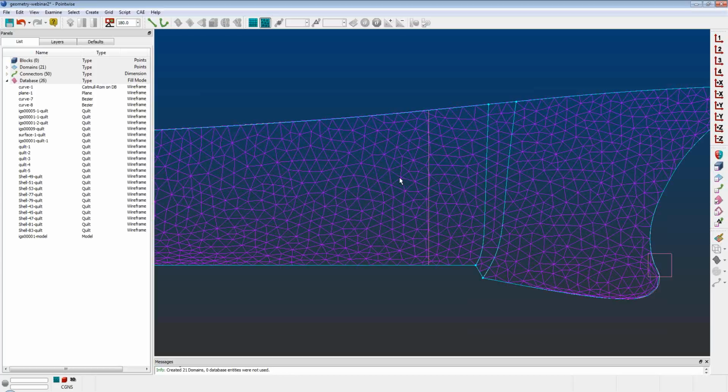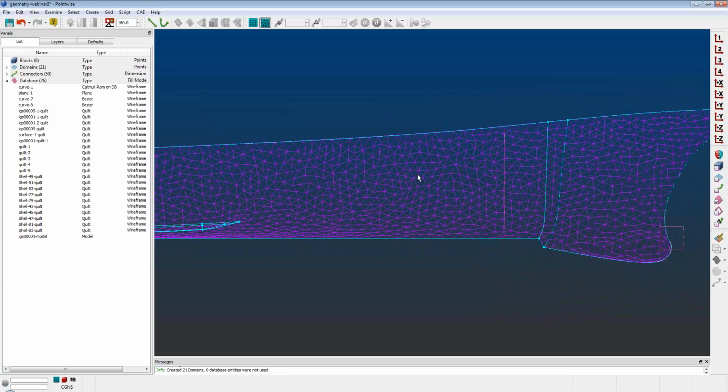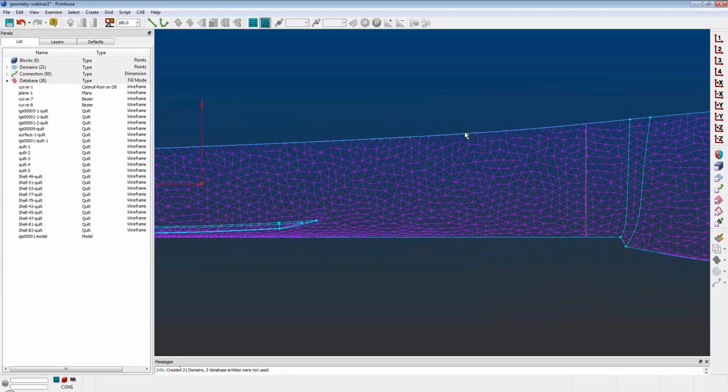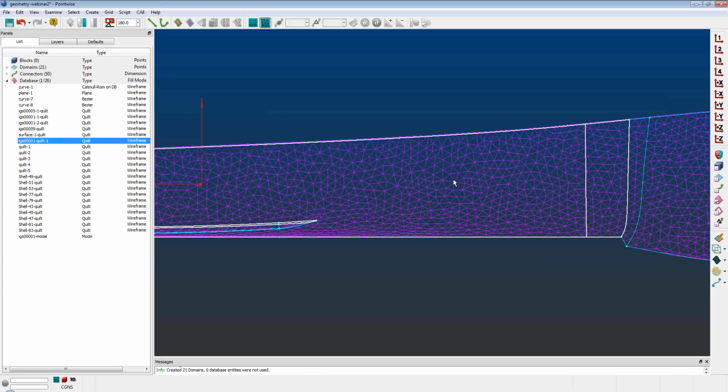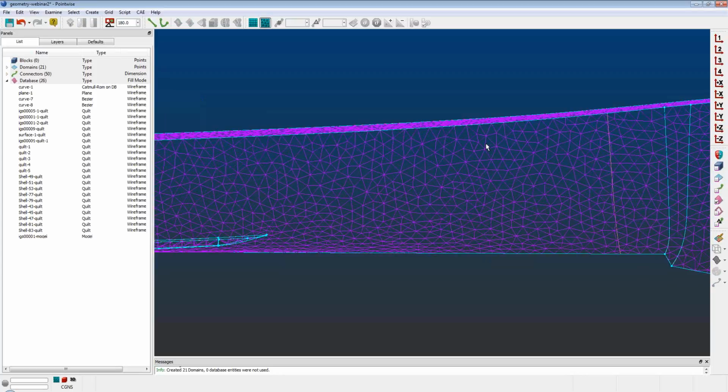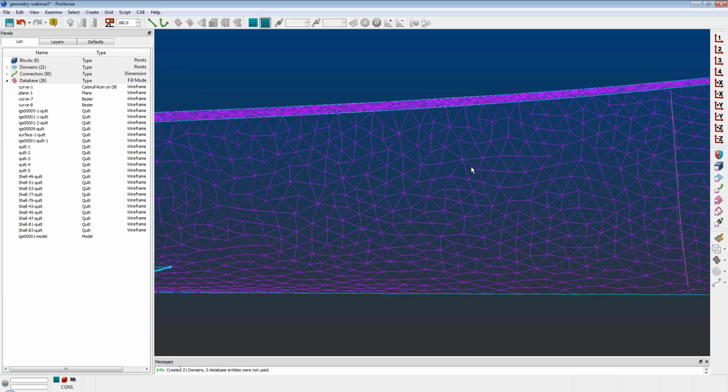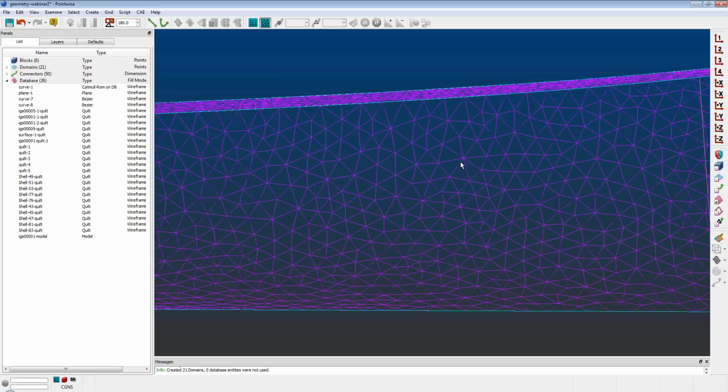So within the internal definition of the surfaces, there are just some ripples, but you're not really wanting to resolve them. Exactly. Hypothetically, let's say this whole surface had exactly what you're asking about. We've meshed on that whole surface, and maybe there are some ripples in that. But remember, the mesh is discrete, so the resolution of the mesh may be larger than those ripples, and it's going to technically just mesh right over top of them. For example, if the ripples were smaller than the edge length of the internal mesh, those would just disappear.